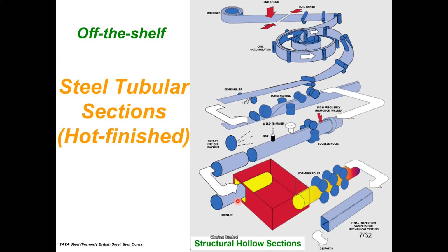If we try to relieve those stresses, then we can make use of some hot bath, just like when you are under stress, you go to a sauna. So after we've got all these things in here, under a hot environment you can shape it again to square, circular, whatever you want. So again, we call it hot finish. Obviously, you can see there's different performance between cold form and hot finish. Again, it depends on the manufacturer and what they have in place.